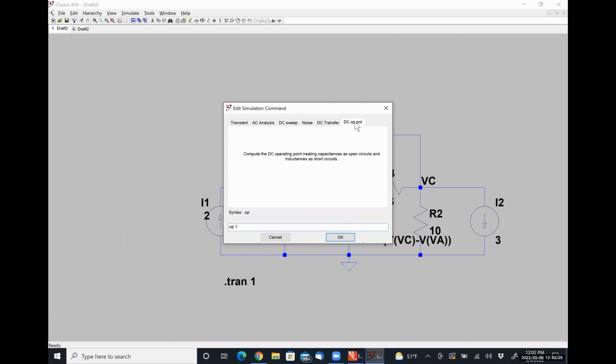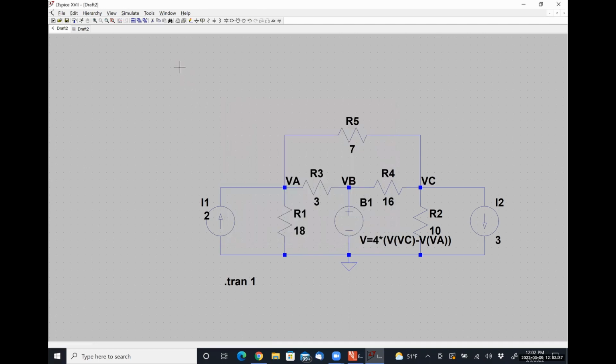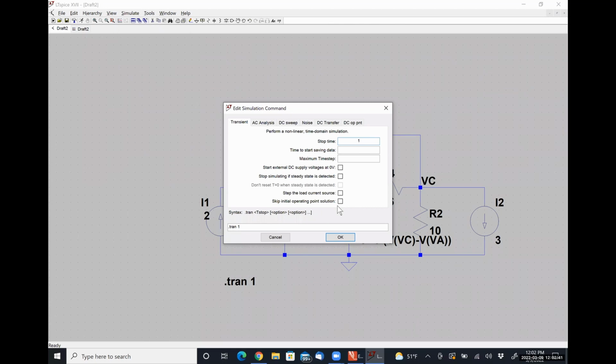For the transient analysis, what about putting a stop time? Let me show you literally exactly what I did. Oh, sorry, you don't leave the stop time blank because you need to tell it when to stop, but everything else, I left it all blank.